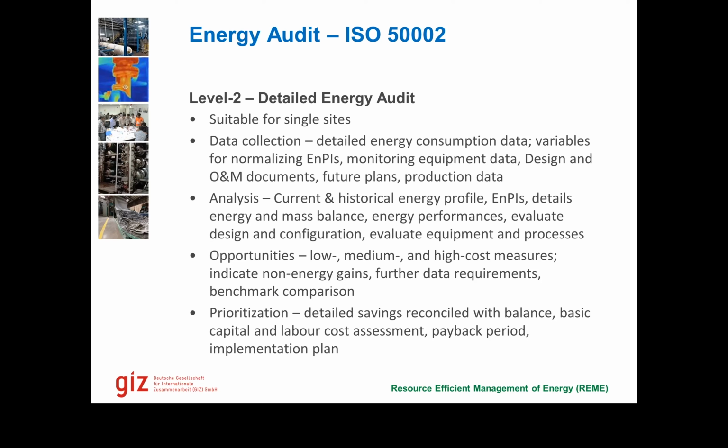Benchmarking could be external, and could also be internal benchmarking. So if we have 4 or 5 machines of the same quality, same type, producing the same product, we could compare them with each other. Okay, machine 1 is consuming 4 kilowatt hours per kg of production, but machine 2 is consuming 4.2. And then we can do a detailed analysis, put data loggers on both machines at the same time, plot their graphs on top of each other and see what is causing this difference. So that is how we can do some benchmarking.